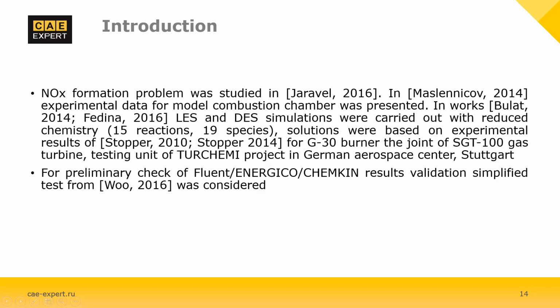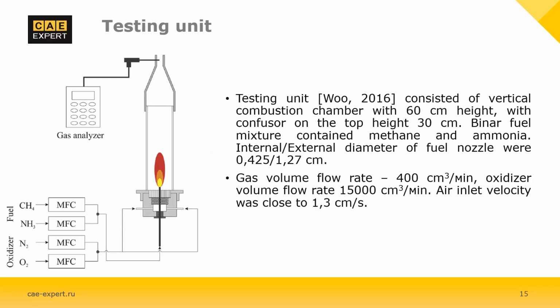The experimental apparatus is a co-flow burner with mass flow meters to supply fuel and oxidizer, and an emission analyzer Testo 300M as shown in the figure. The fuel was supplied through a mixer filled with glass beads for homogeneous mixing, and used chemically pure methane mixed with ammonia. The volume ratio of ammonia in the fuel was changing.